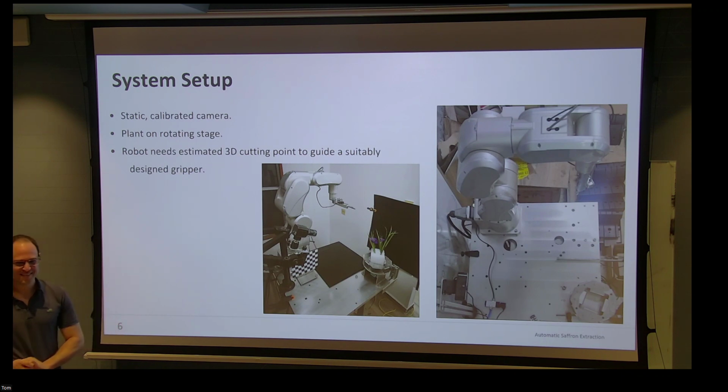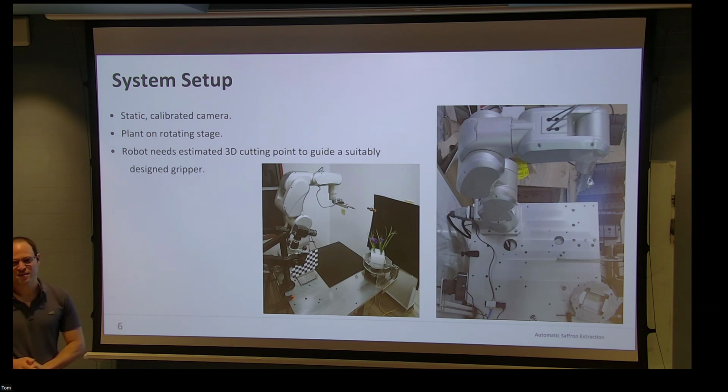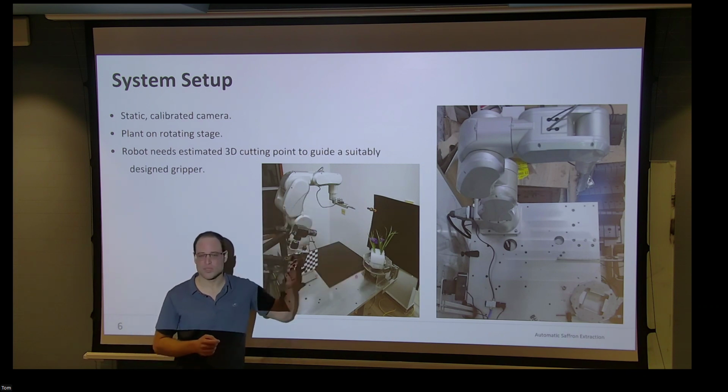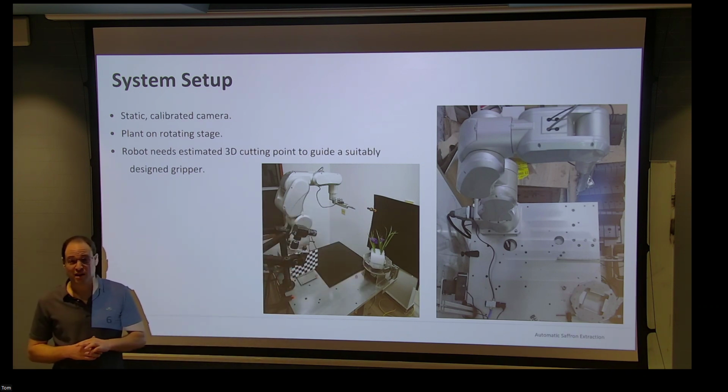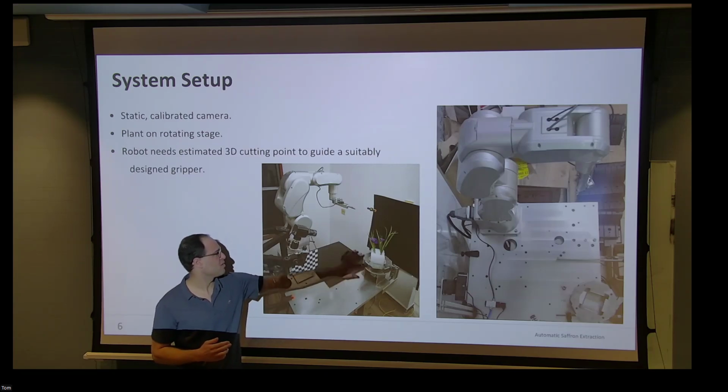Okay, more questions? Some more questions, some suggestions. Talking about the movement of the camera, the movement of the robot, whether it's an arm or an axial one, isn't there supposed to be some hand-eye calibration between the picker and the camera itself? It's a good point, between the robot and the stage. There is hand-eye calibration between the camera and the stage, so it's the same thing. We have it from the camera to the stage. Now we can do it from the robot to the stage too.